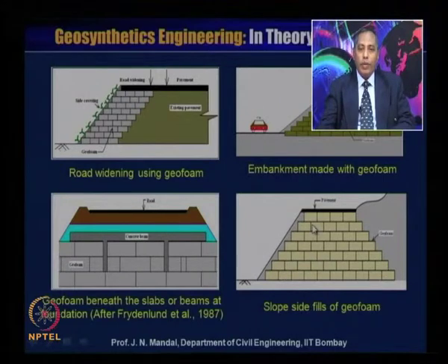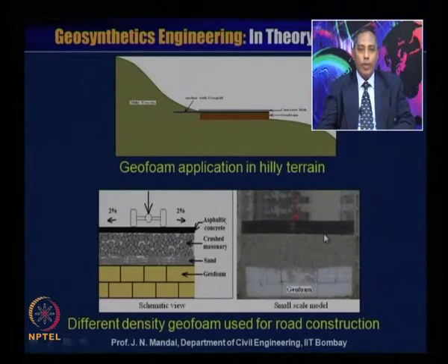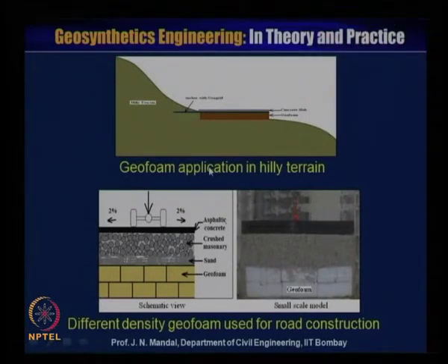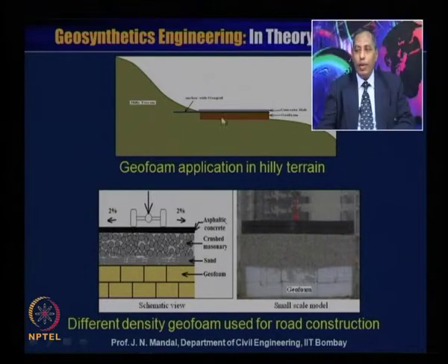And here is the slope side fill of geofoam. Any slopes in this area, you can see like this. So you can place the geofoam material and construct the slope side fill with the deployment of geofoam. Some geofoam applications are in hilly terrain, where it is sometimes very difficult to construct, but you can simply place the geofoam material and concrete it, so you can construct the road.